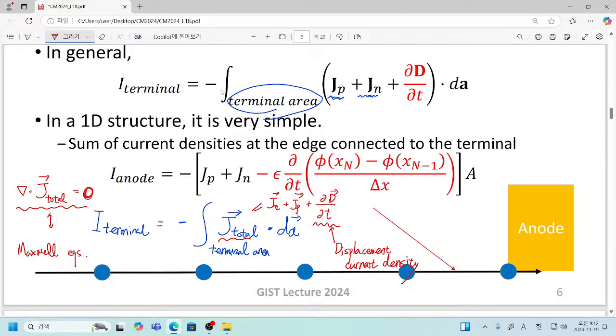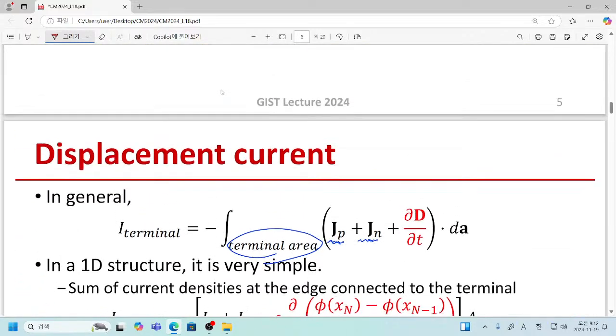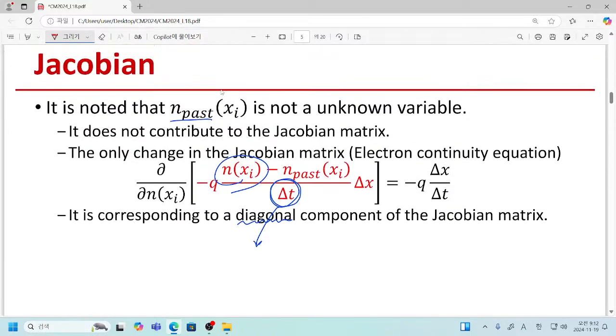So simply speaking, although you have already made many good implementations for your DC calculation, when you consider your single device, the only modification to your Newton-Raphson method is changing your residue and your Jacobian matrix, and then you will get the solution.